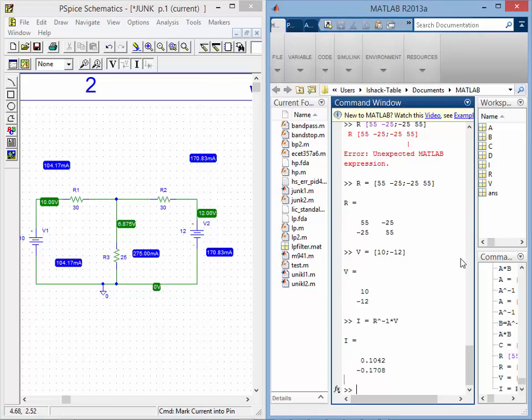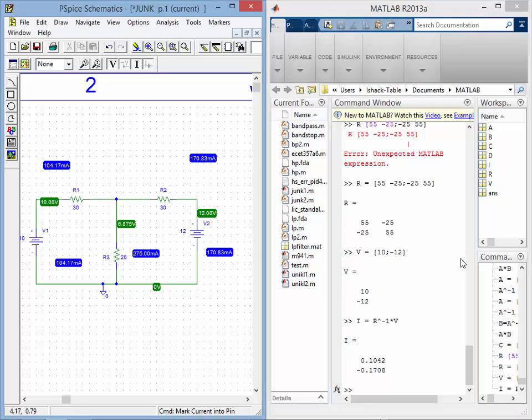So now the thing here is, this one here is a negative number, but if we click on that, you can see that arrow is going in this direction. We drew I1 going clockwise. In reality, it's coming out of the positive side of the 12 volts, and it's going counterclockwise. So that's where that negative comes from. Both this one is going down and this one is going down.